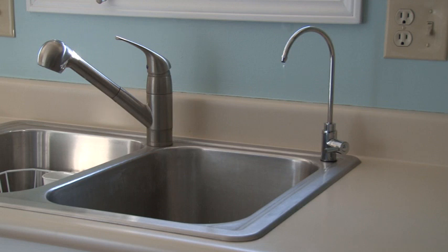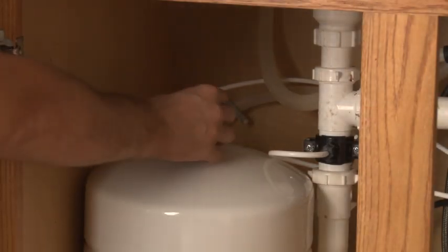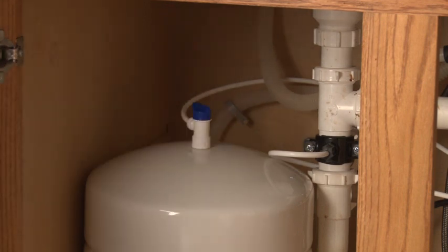The first water that discharges from the faucet will likely be black or gray. This discoloration is merely fines from the carbon cartridges and will clear up when flushed. Close the faucet and wait a few minutes or until the water no longer flows to the drain before checking for leaks. If there are no leaks, open the ball valve on top of the storage tank.